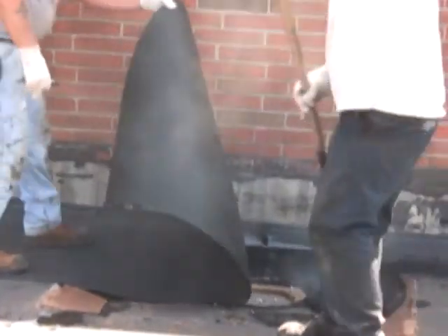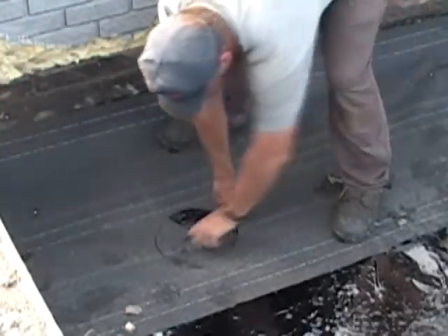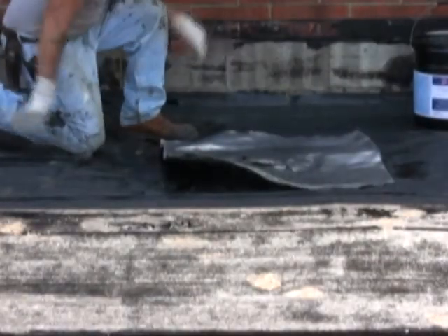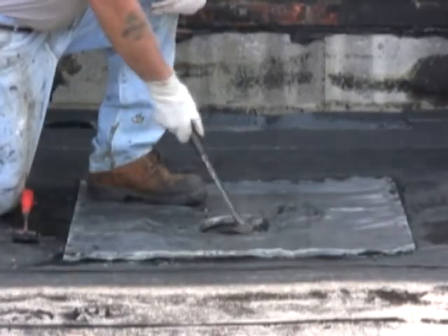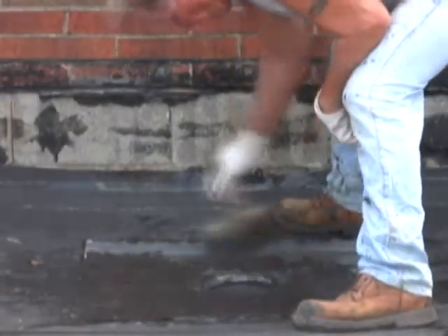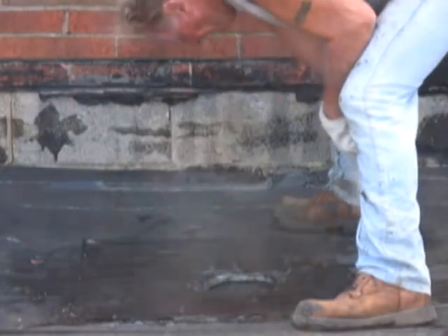Run roof system plies over drain. Cut out plies inside drain bowl. Set the lead or copper flashing, 30-inch square minimum, set in a 1/4 inch bed of roof cement. Run the lead or copper into the drain a minimum of 2 inches. Prime the lead or copper at a rate of 100 square feet per gallon and allow to dry.